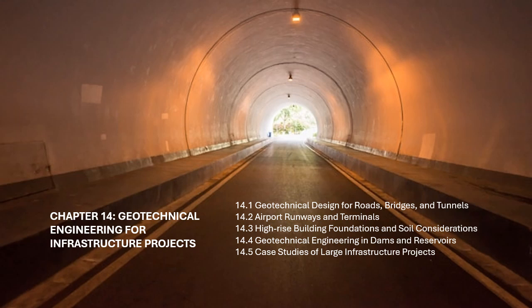Groundwater conditions. Groundwater can complicate foundation design for high-rise buildings, especially if the water table is high or fluctuates seasonally. Groundwater can lead to uplift pressures, complicate construction techniques, or even cause soil erosion or weakening. The design of drainage systems and groundwater control measures is crucial for preventing water-related issues.